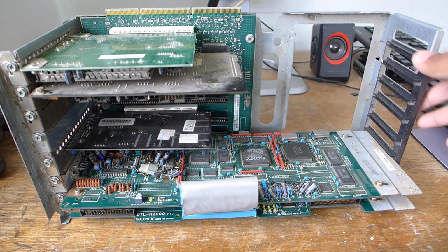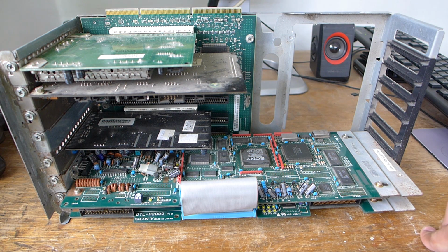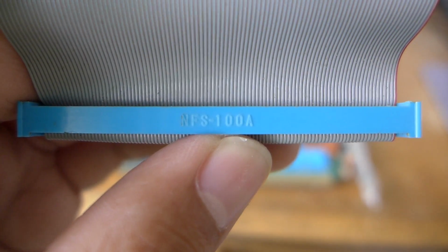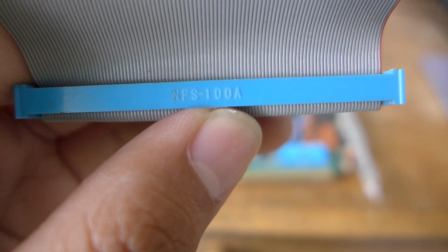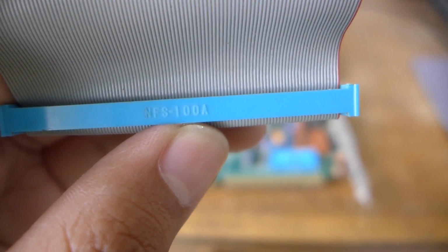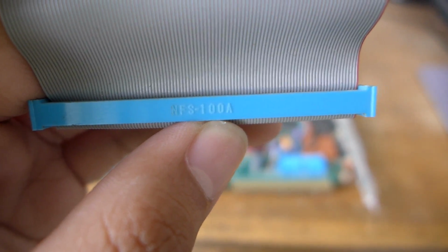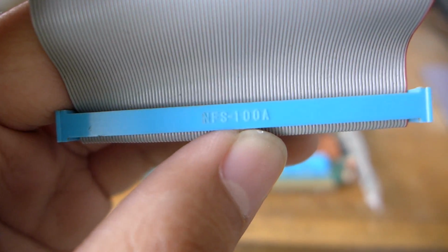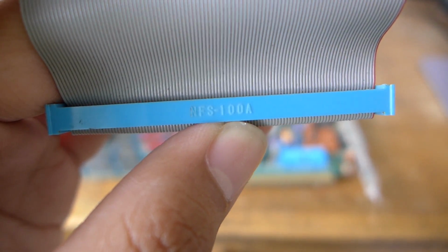I don't know, I haven't identified what connector it is, but looking through their connector database should do the trick. I'm gonna be taking these boards out of the cage so I can show you the jumper settings which you must set before you install the boards into your system. Apparently the connector for the ribbon cable to connect the DTL-H2000 boards together is a Yamaichi NFS 100A. So if you have a pair of DTL-H2000s but don't have the ribbon cable, you can just try to source these connectors and crimp your own cable if you can.